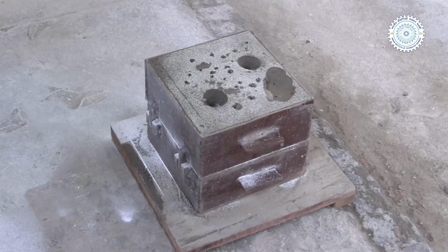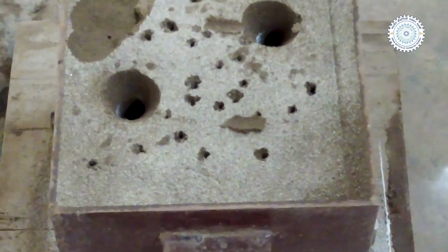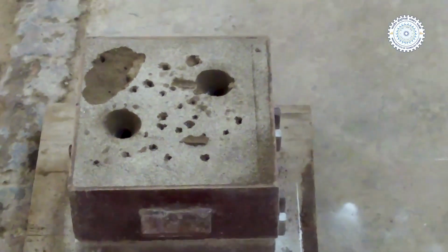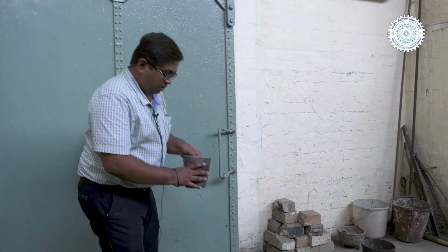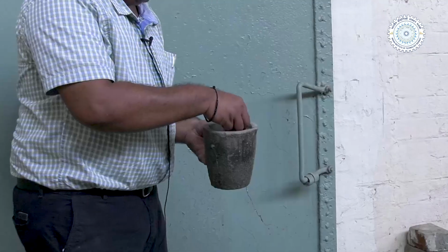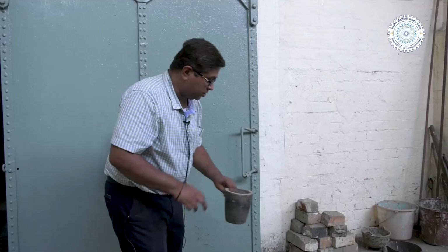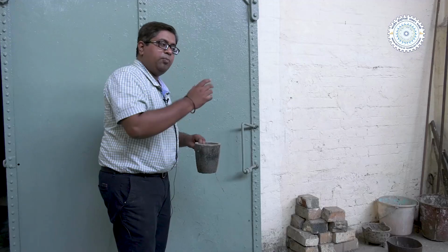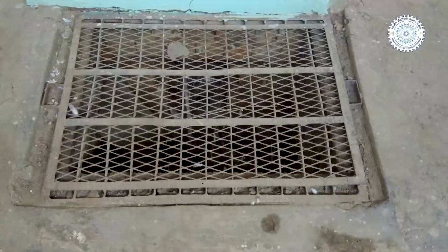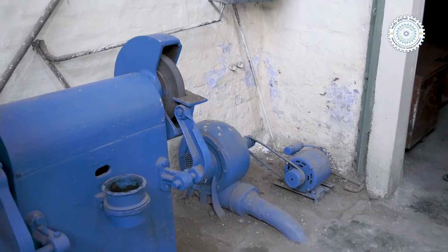Now you can see this entire mold box is ready for pouring. The material used is lead. Now this molten metal is ready. This is our crucible in which you place the raw material. In this case we are using lead. Lead will be placed here, and this entire crucible with the help of tongs will be placed in this pit furnace, and the material will be melted and made ready for pouring into the mold cavity. We have a blower here with continuous supply of air to keep it hot.